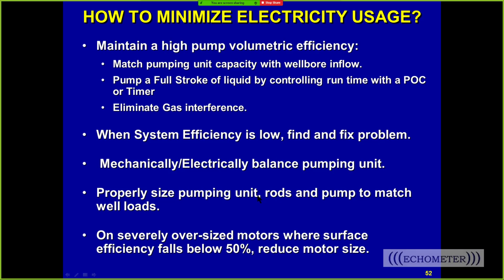Don't use a giant pump unit to pump a little bitty load. Make your unit match the requirements of the well. And when your motor efficiency falls below 50%, it's an oversized motor, and efficiency drops really low, then you can reduce the motor size. But be cautious about changing just one motor size, because usually the motors are about the same efficiency, and you may not gain much by changing a motor from one size to the next. If you're going from a 40 to a 30, if they're both NEMA motors, they're both going to be about the same efficiency.